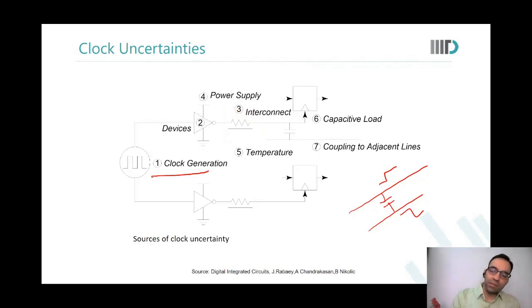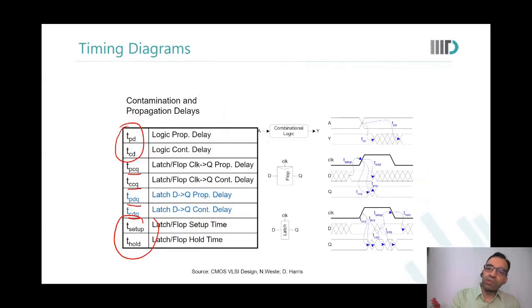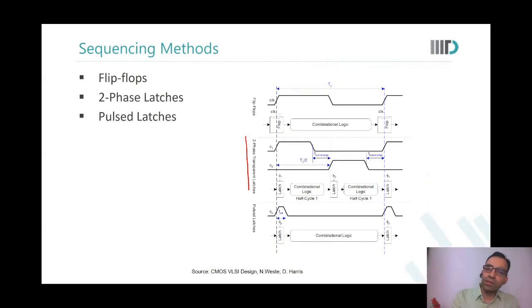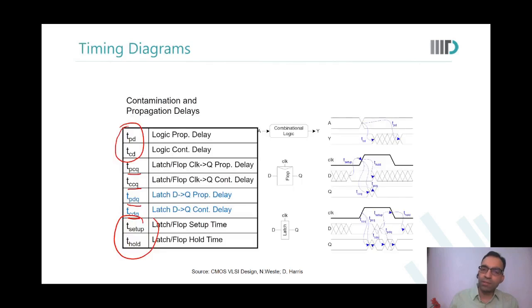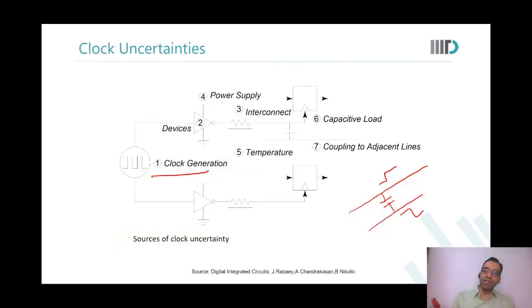What we are saying is, see, here, we were saying that what is the delay between one flop and another. Both the pins are being referred to as clock. But what can actually happen is that one flop is experiencing delay through this path, and the other flop is experiencing delay through this path.